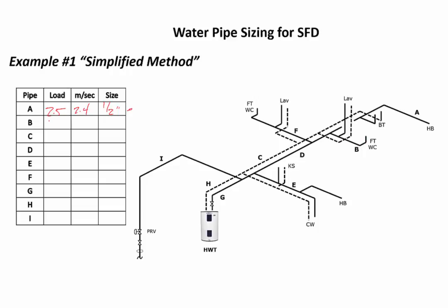The velocity is cold, so it could be 2.4 meters per second. However, again, as a supply pipe, could be sized directly from table 2632A. Minimum size is 3/8 inch for the supply pipe. After the wall stop, then there would be a toilet riser that would connect to the tank. Okay, C is finally a distribution pipe, and the remainder of this piping system we will size now from table 2634. C is a hot pipe, this hot line here, that's supplying hot to a lav, hot to another lav, and to a bathtub.